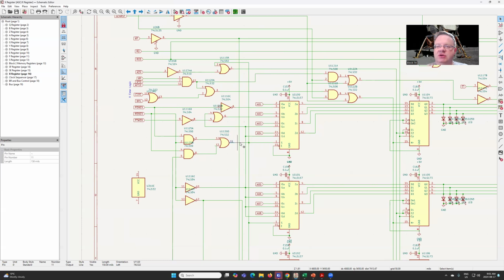And then we have our selector that we use to say, if none of these are asserted, so if the A2X is asserted, we will load from the A register. If one of these others is asserted, then we'll load from the second option within our 2-to-1 selector. The rest of the logic here is to generate the appropriate values for that second option. If it's a P1X, it's pretty simple. Because it's negative logic, we just invert that. If this goes to 0, we turn this into a 1, and we load that into the first bit of our register. So that'll give us logic 1.